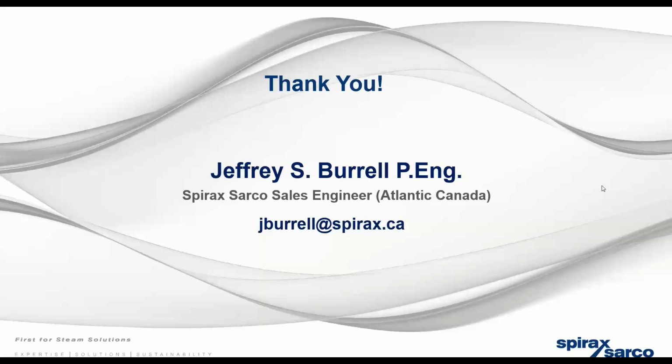But yeah, if it is not a lot of high pressure condensate, depending on what you have as well, Mustafa, there might be ways to do this. If you have piping installed already, the best, as Jeff said, is separate it. I know it might not always be an easy thing to do, but there's ways of doing condensate mixers, which might reduce it a little more as well. Agreed.